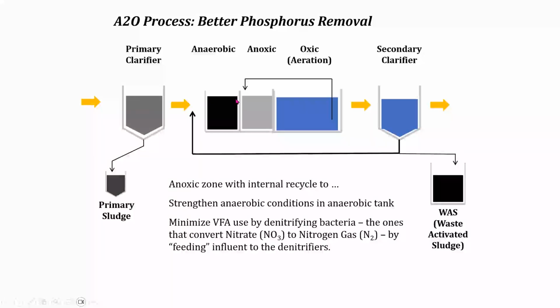And then you want the flow leaving the anaerobic zone going into the anoxic zone, so you just grab it wherever you can, either leaving that or coming into the anoxic. You don't want the return in that. And you measure the soluble phosphorus, the return, the internal recycle. And you're looking for that 3-to-1 ratio. You can take the sample and settle them and just pull the supernate off. You can actually filter the samples, but whatever you do, do not cook the samples. We're looking for the 3-to-1 ratio of the solubles.